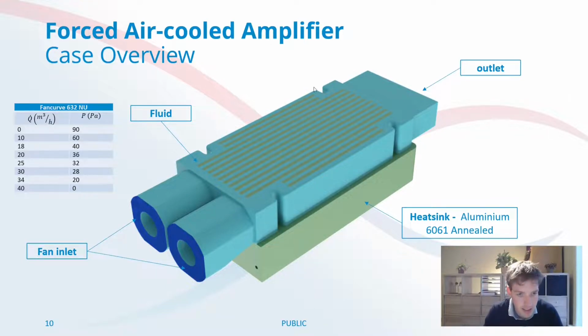About the fans or the fan inlets, of course, if you work with a fan, then you need to give a fan curve as well. I have put a table in here with the fan curve. In the Diabatix ColdStream platform itself, there are already a lot of fans implemented in the library. Of course, not all of them, and if you want to use a specific fan like I want to do in this case, you can simply add that one. I will also cover that when we are at the platform again.